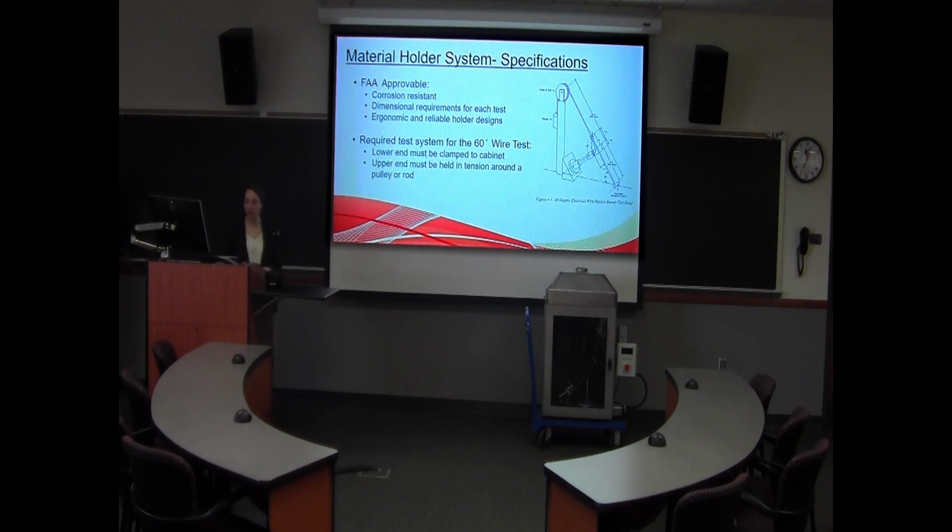So the ultimate goal of the material holders for each test is to accurately secure the sample of specified dimension over the burner at a distance determined by the FAA. But we also wanted to make a design that was easy to manufacture and easy to use and affordable. So out of the 4 tests, the 60-degree wire test had the most complex requirements that we had to accommodate.